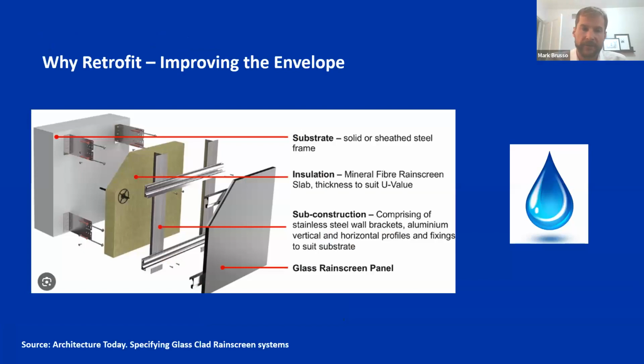And the other important concept of retrofitting the building envelope is that we are also equipping it with a very robust system, in the context especially of rain screen systems. With this type of technology we are increasing the water shedding, insulation, and energy saving capability of the building to a new level. And again, on the right, my symbol for that being the raindrop. The most important part, in my opinion, with this improvement is keeping water out of the building envelope and keeping it on the outside. So all these improvements are very intimately associated with retrofit construction.